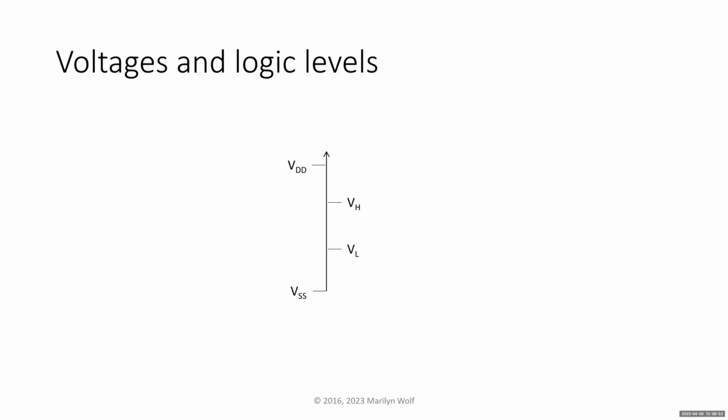Okay. So we have a scale of voltages in which the inputs and outputs can reside, VDD at the top and VSS at the bottom. In steady state, as you saw, the logic levels go to one of the power supply levels, VDD or VSS. But setting a single voltage to be a logic level is unwise and really impractical. So let's come up with some ranges for voltages.